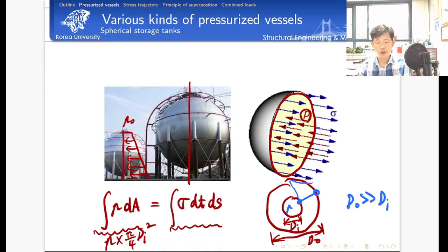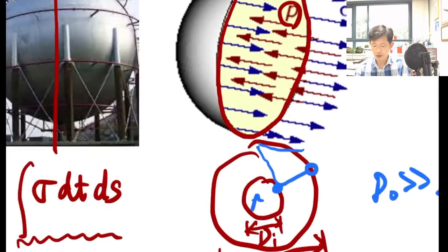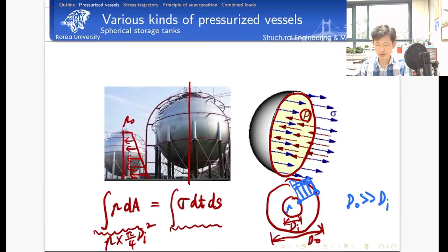But here we'd like to use the concept of plane stress, okay, the plane stress, which means if you introduce that simplification, the normal stress in the thickness direction is constant. This is our simplification. So here what we want to do is, instead of this nonlinear distribution, we want to consider the normal stress is constant over the thickness. Okay, this is our simplification. So because of this simplification, we can take it out here. So our calculation becomes much simpler.